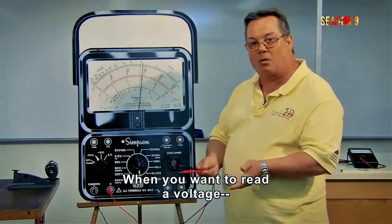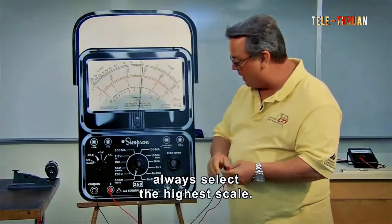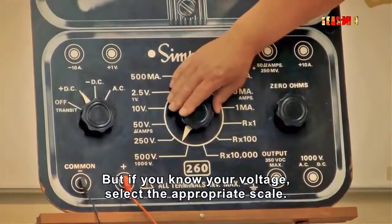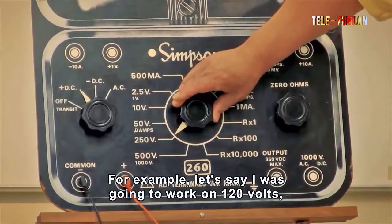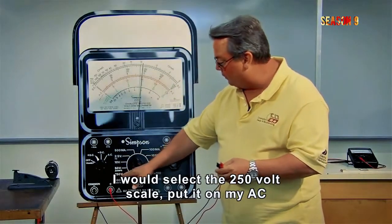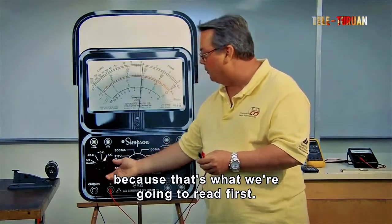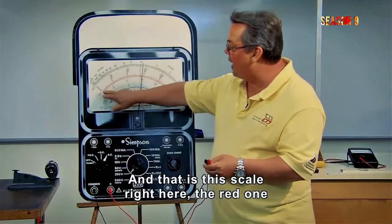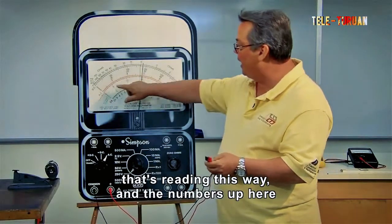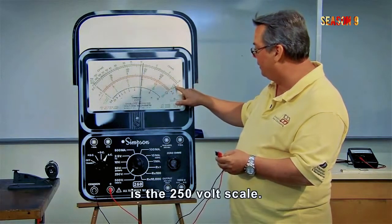When you want to read a voltage, if you don't know the voltage, always select the highest scale. But if you know your voltage, select the appropriate scale. For example, let's say I was going to work on 120 volts. I would select the 250 volt scale, put it on my AC, because that's what we're going to read first. And that is this scale right here, the red one that's reading this way. And the numbers up here is the 250 volt scale.